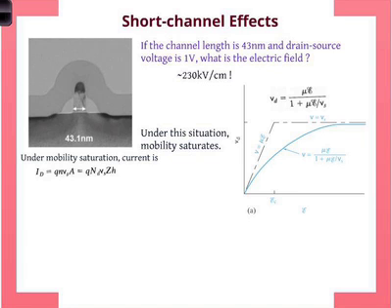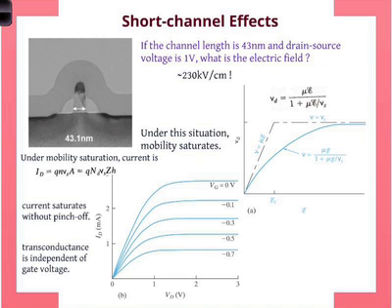Yes, that's right. What did someone say? The width of H, or the amount of H. Yes, it is the area. It is H. Remember, H depends upon the gate voltage. Also slightly on the drain, but primarily on the gate. Remember, we derived this. So although the current is saturated, you can still amplify it with the gate control voltage. Exactly the same situation. Just that the saturation current calculation is different. That's all. Okay, so keep that in mind. And this is what's shown here.